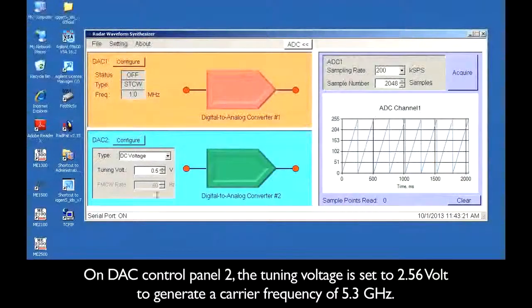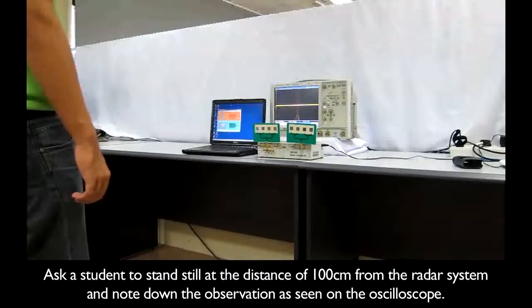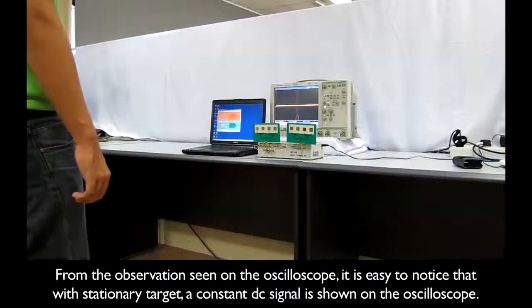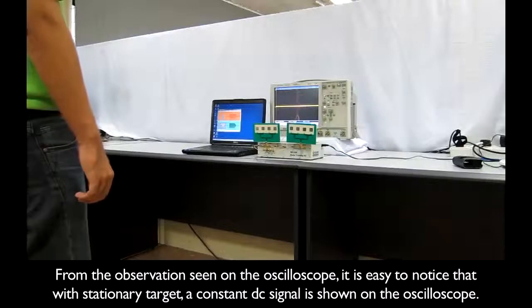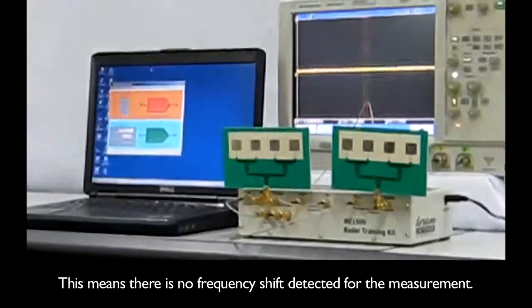On DAC control panel 2, the tuning voltage is set to 2.56 volts to generate a carrier frequency of 5.3 GHz. Ask a student to stand still at the distance of 100 cm from the radar system and note down the observation as seen on the oscilloscope. From the observation, it is easy to notice that with a stationary target, a constant DC signal is shown on the oscilloscope. This means there is no frequency shift detected for the measurement.